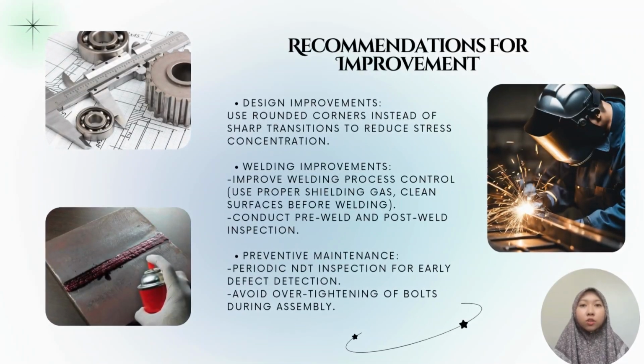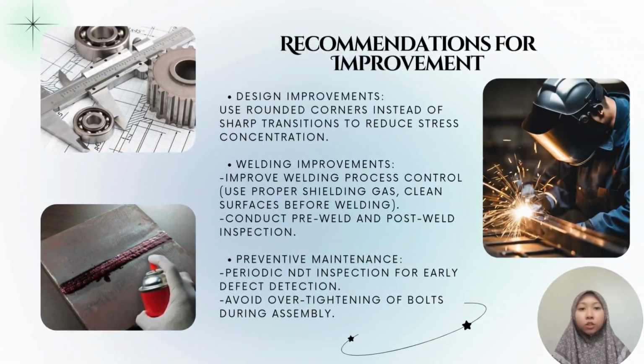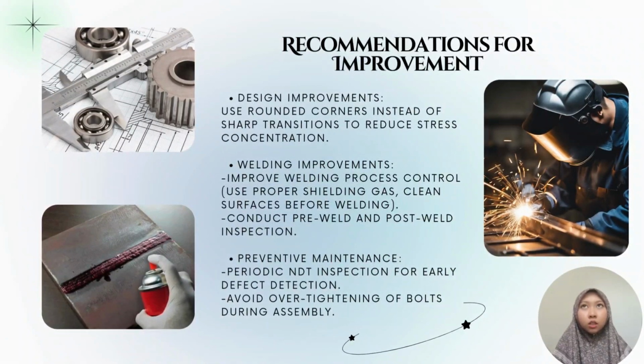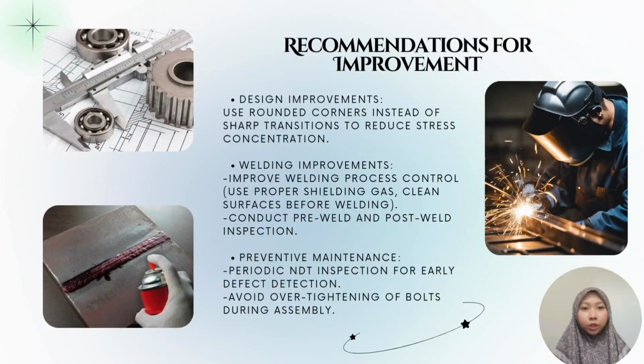Okay, now let's go over the recommendations for improvement based on the risks identified. Okay, first, we recommend design improvement. It's advised to use rounded corners rather than sharp transitions. This helps minimize stress concentration and improve overall durability.